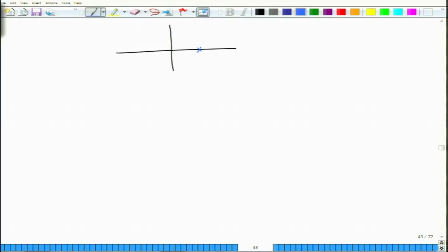So, for the BPSK constellation or for the on-off keying constellation that we will consider first, you have two symbols which are say 0 and 1. So, these are the symbols that I have transmitted. For 0 you transmit nothing, and for 1 you transmit some power. In terms of the constellation, this is sitting at 0 and this one is at square root of Es. Please note that as I have told you many times, I could have used Ps also, but I am sticking with the energy considerations here because that is more common in traditional digital communication literature.